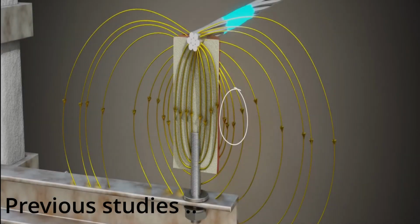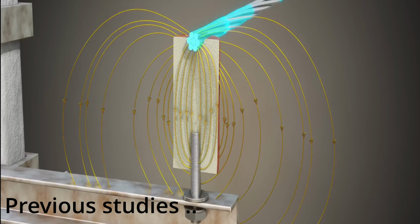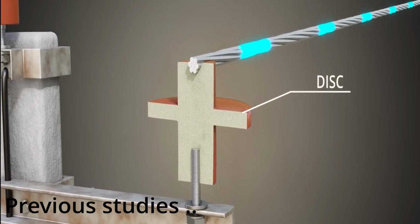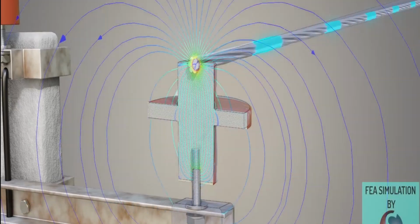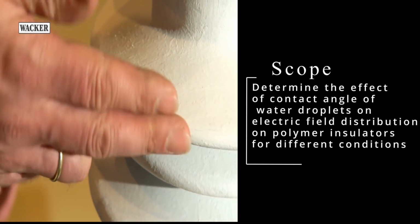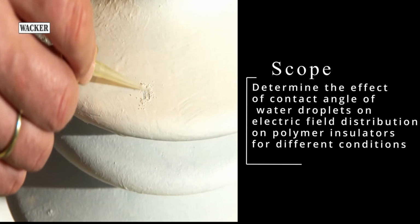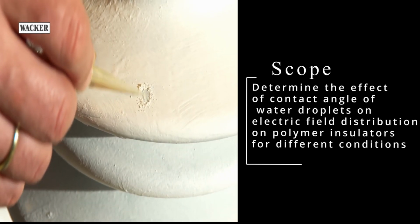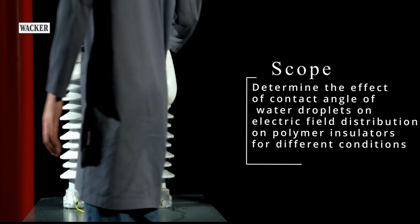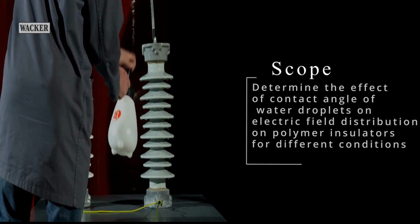Previous studies have found that water droplets affect the electric field distribution, but no detailed studies have been carried out to analyze the effect of contact angle of water droplets, with different pollutants, on the distribution of the electric field. The scope of the study was to determine the effect of the contact angle of water droplets on electric field distribution on polymer insulators for dissimilar water conditions and polluted insulators for environmental conditions in Sri Lanka.